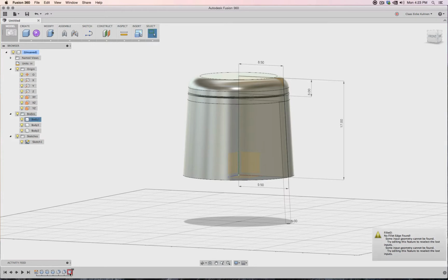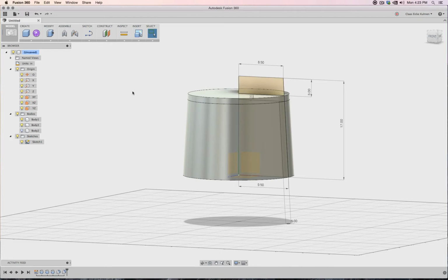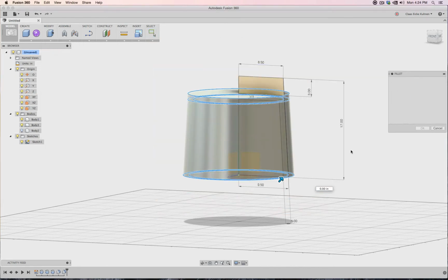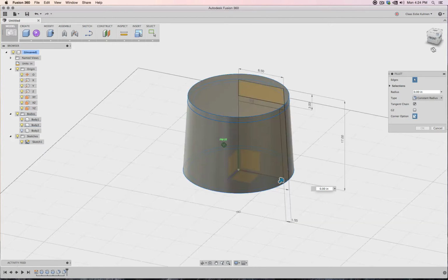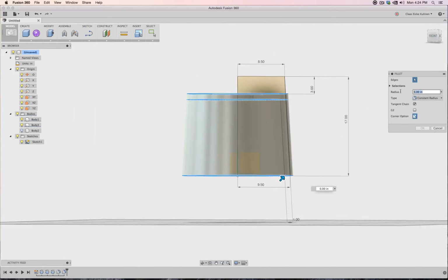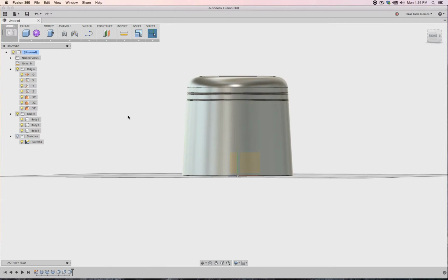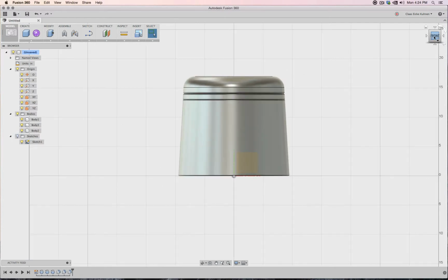Now those fillets again are being cranky. So maybe let's delete that one. Nope, not edit, just delete there. So that's that one, that one. Okay, let's hide this object. And the main reason why I wanted to hide it is I'm going to fillet, drag over everything I have. You see it selects all those edges. In here, maybe now at once I type in 0.1. Okay, and then I can show this object again, hide the sketch, and take a look what we have.